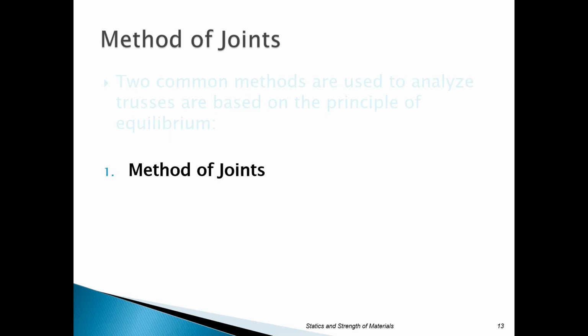It's kind of messy, but it's very foolproof, because when you get done with this method, if everything doesn't resolve to zero at the end, in other words, sum of forces in X, sum of forces in Y, don't resolve to zero, then you've got a problem in your analysis. So you've done something wrong. The downside is it doesn't necessarily tell you where you went wrong. So if you blew the first joint and brought that all through your truss, every joint is essentially going to be wrong. So that's the problem.